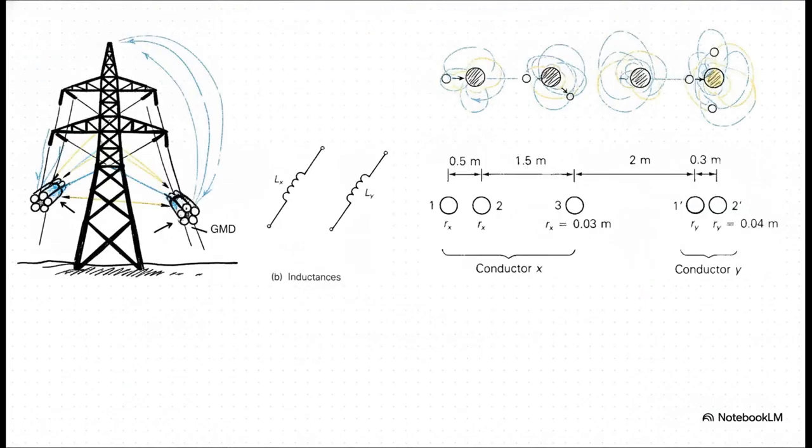Okay, let's bring this out into the real world. Think about the physical towers, those giant metal structures you pass driving down the highway. You actually can't calculate a line's inductance, its capacitance, or its resulting SIL without knowing its exact physical geometry. Engineers rely on 2 critical metrics to do this. First is the geometric mean distance, or GMD.